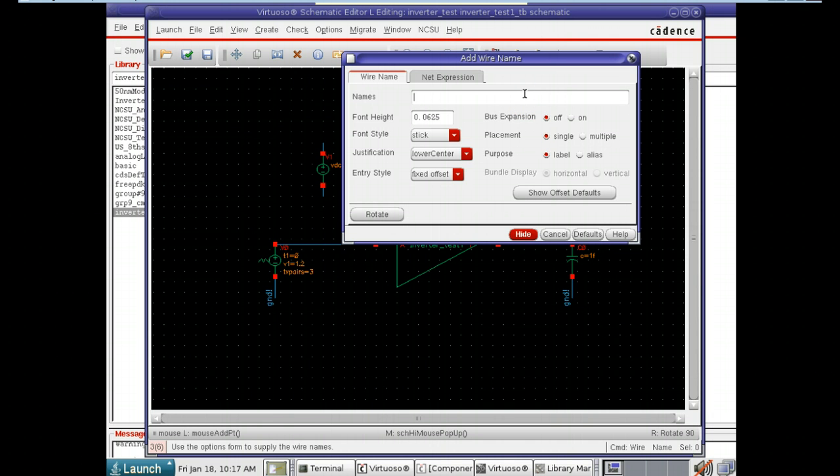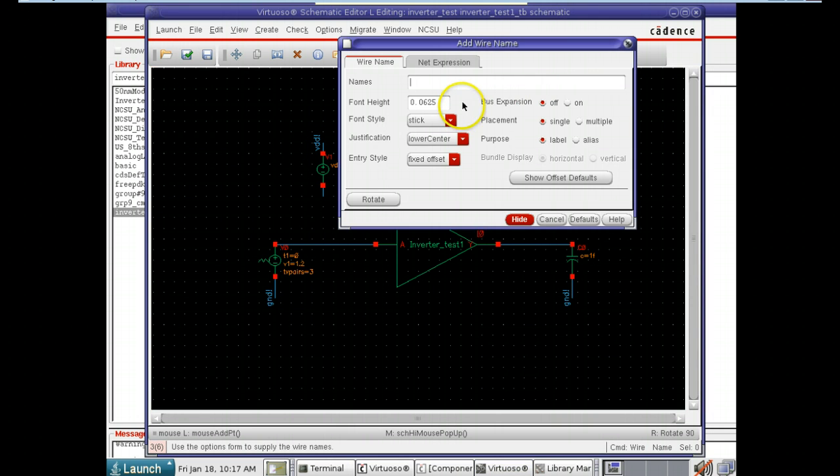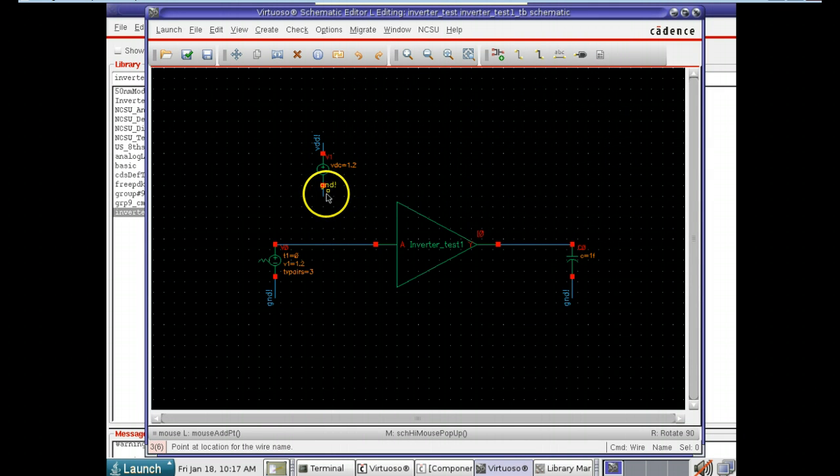You guys already know about GND exclamation point, so we're going to be using VDD exclamation point for our positive. Basically, this output here to VDD exclamation point is going to go to anywhere we have a supply net set up with VDD. So that's the inside of our CMOS inverter.